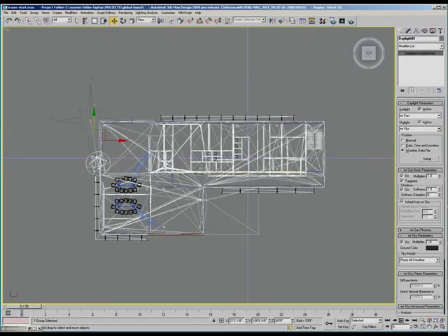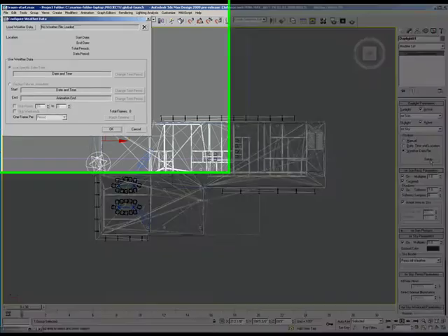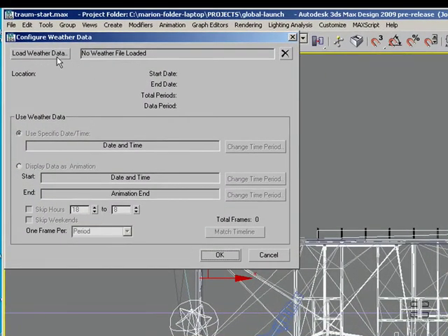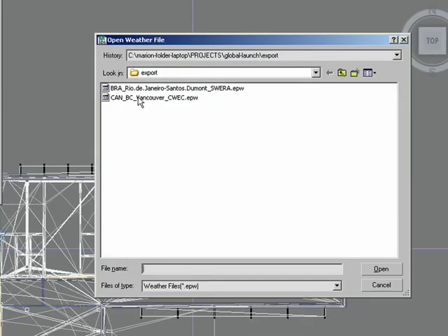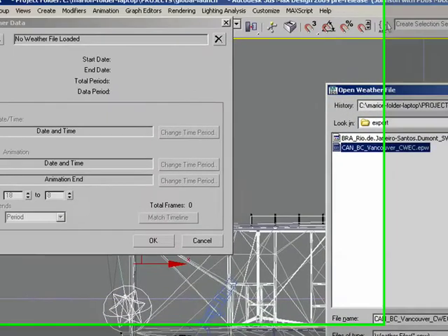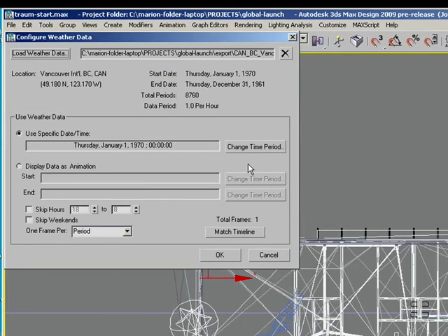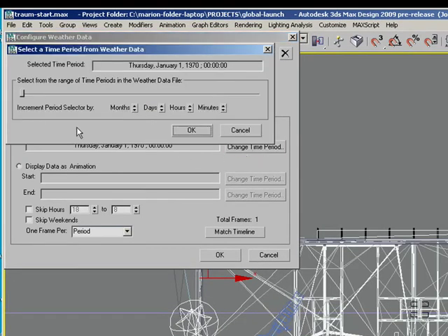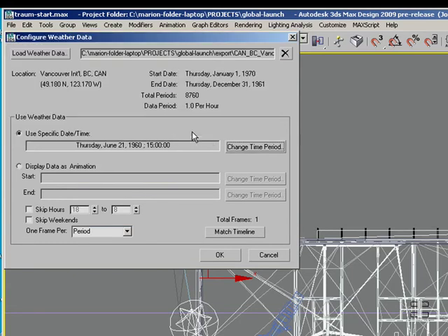What this website does is collect information about weather conditions around the world with historical data. So by using the EPW file in your scene, you're guaranteed that your lighting analysis is exact and based on measured data. From here, you can pick a day, typically solstice or equinox, and a preferred time. For this particular scene, we'll do June 21st at 3 p.m.